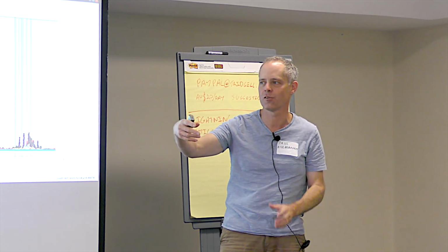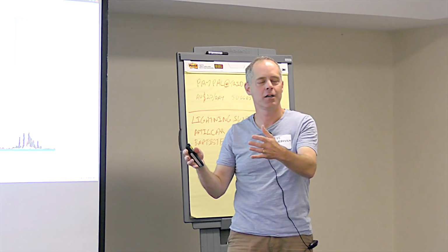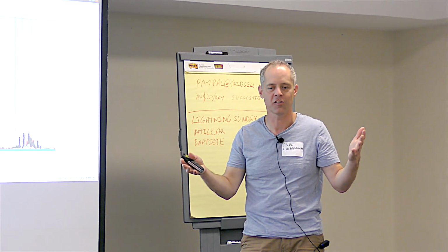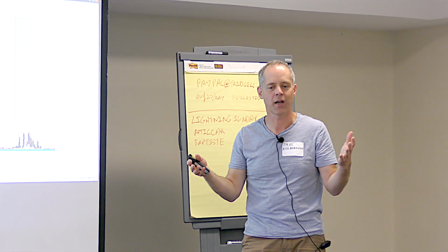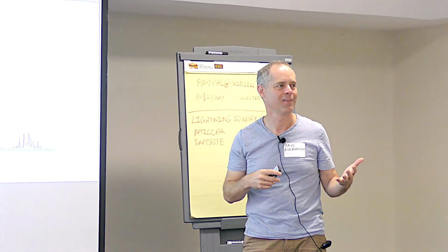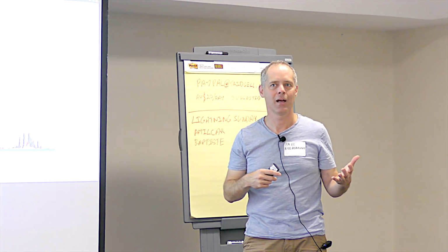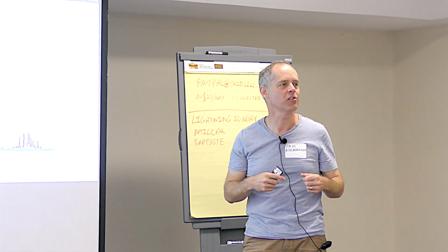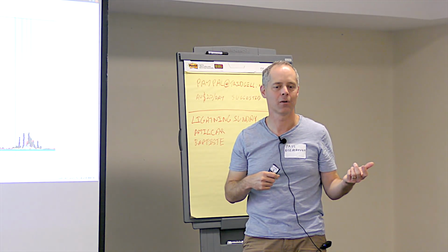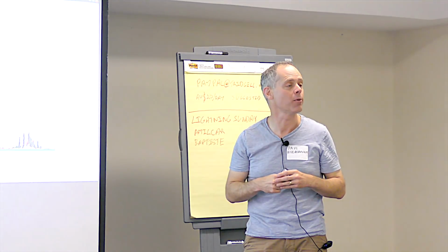The vehicle moved east. The GPS says it's moved east. The inertial navigation says it's moved south. The EKF's looking at this big inconsistency. If it's large enough, it will say, all right, I reject the GPS, and then 10 seconds later, I'll try to do a reset. Whereas the root cause could have been the fact that the yaw was out by 90 degrees.